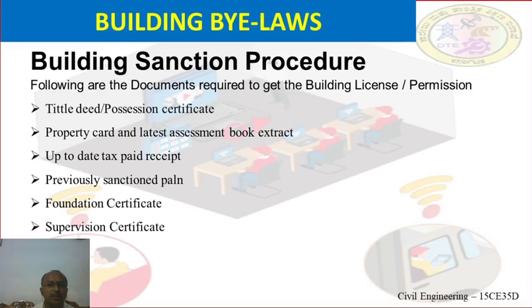The plate load bearing test is one of the tests conducted for the foundation to know the existing soil condition, whether it is black cotton soil or hard soil, which decides the foundation details. While constructing the building, we may have problems if we have black cotton soil, which, as you know, is the enemy of engineers.